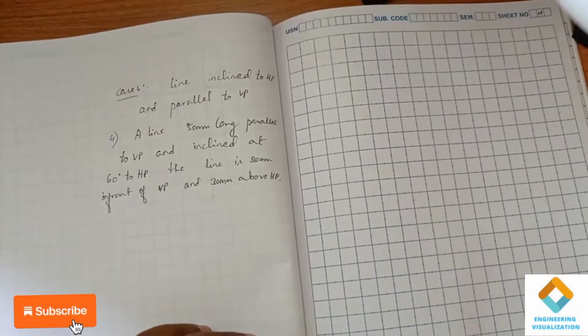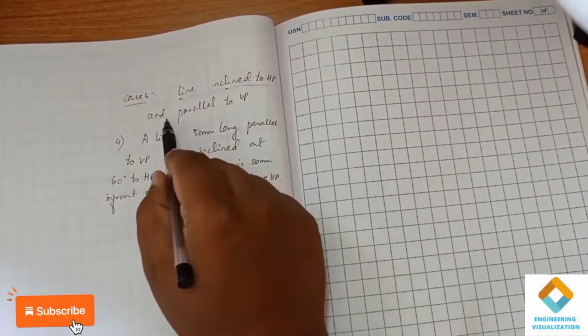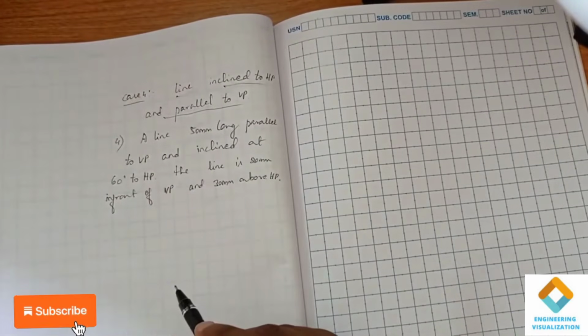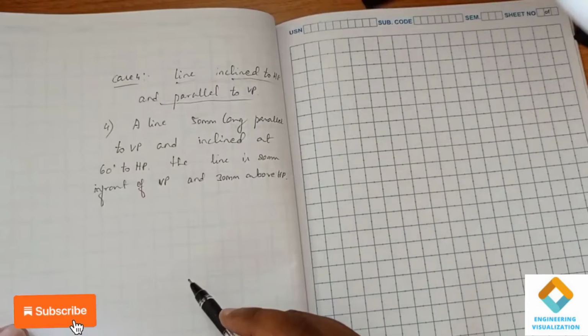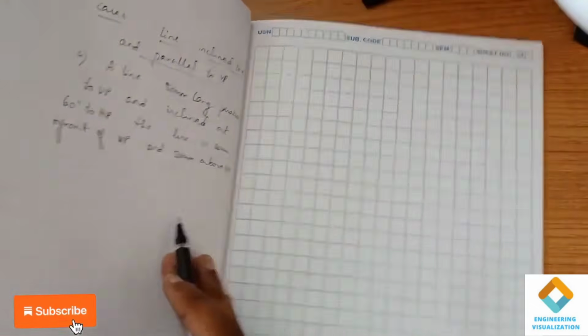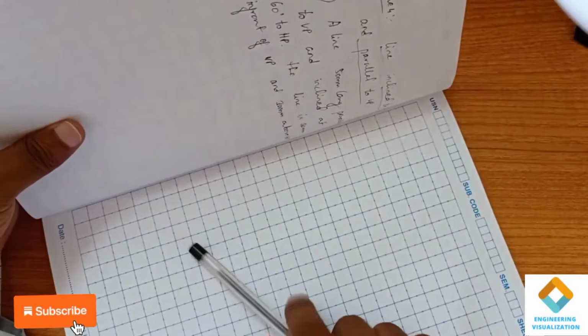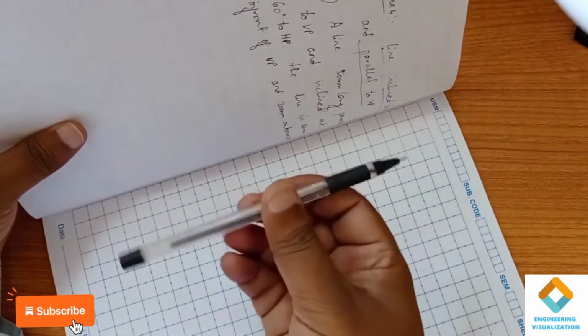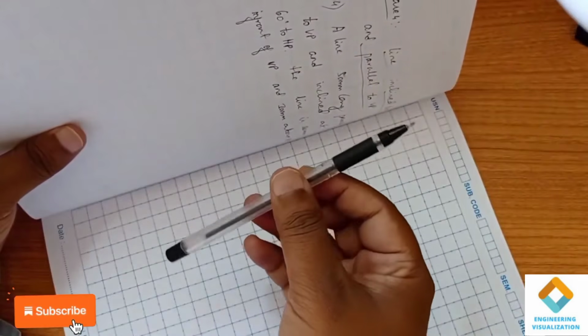See, a fourth case in projection of line. The line is inclined to HP and parallel to VP. So here we have to give inclination to HP and make sure the line is parallel to the VP. So how is it done? You see it here. This is the vertical plane, this is the horizontal plane. In this condition it is both parallel to HP and parallel to VP. Now I am going to give inclination like this.